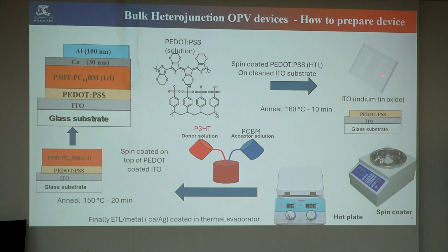So I'm giving the example of the indium tin oxide. You see on the glass substrate, you can see some pattern. This is what you have in the device, right? We need to have some patterned ITO, because the ITO is everywhere. Then on top of that we have to coat aluminum as well, so we do some type of patterning.